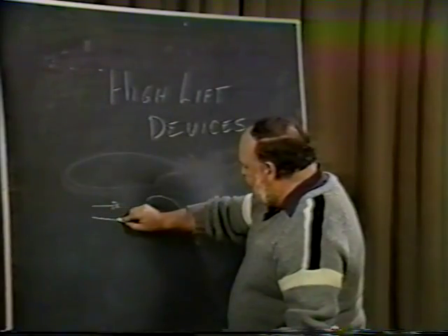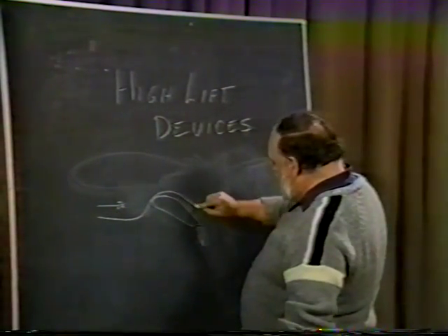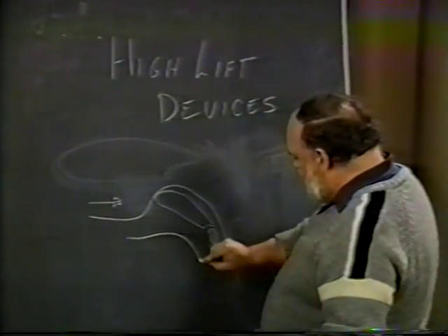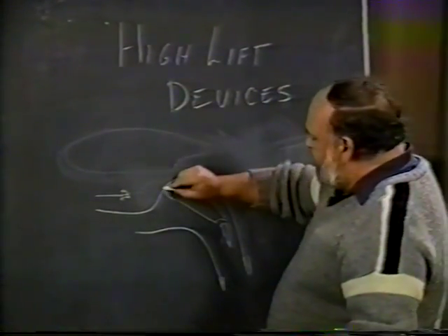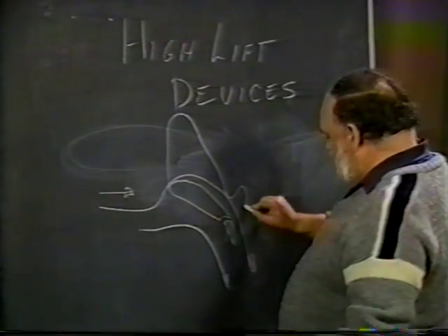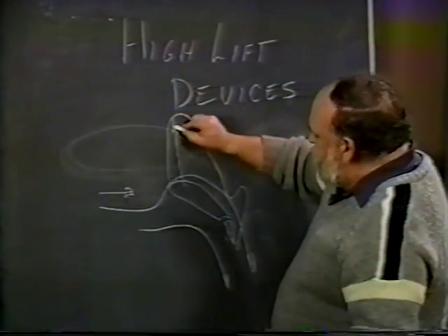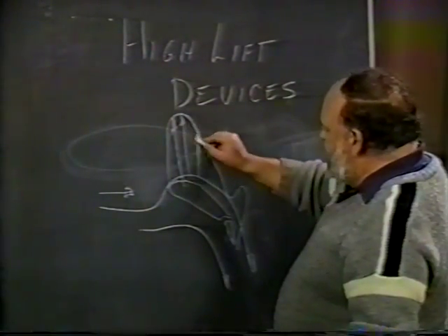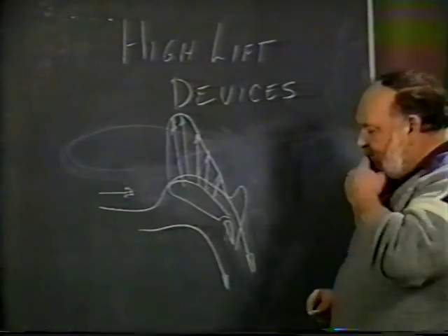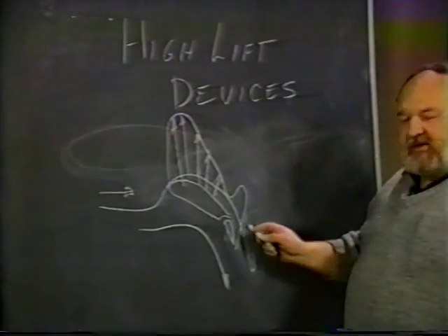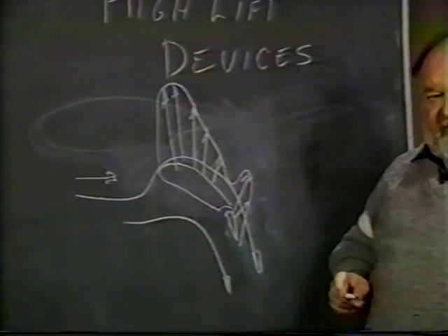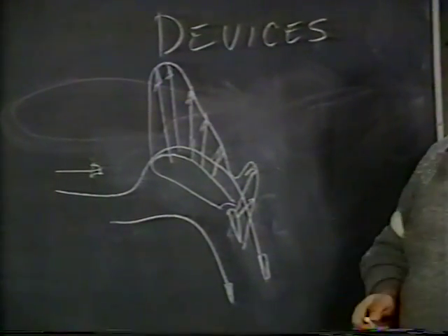What's going to happen is the air is going to come up over the wing, speed up and come down the trailing edge here. The air on the bottom will, of course, be deflected down too. What this will do will produce a lift pattern that is something like this. These could be visualized as vectors demonstrating how much lift, or force, is being exerted on the airfoil. A lot of people believe that when you deflect the flap down, it produces a low pressure above the surface of the flap itself, and that produces lift. Yes, it does.